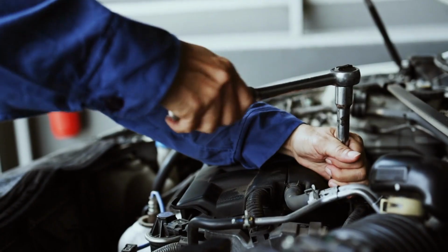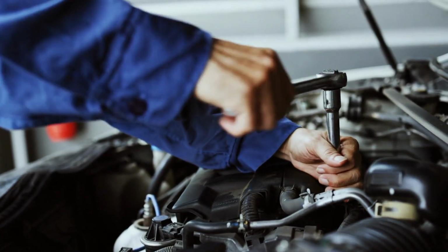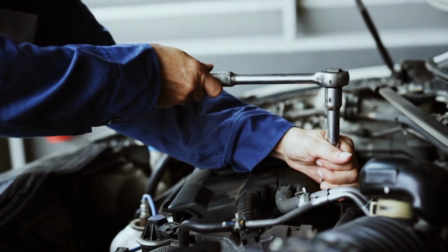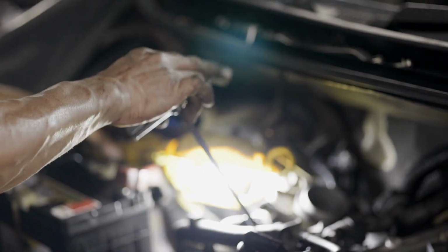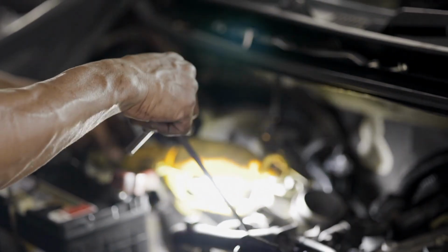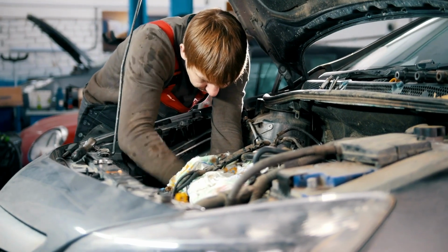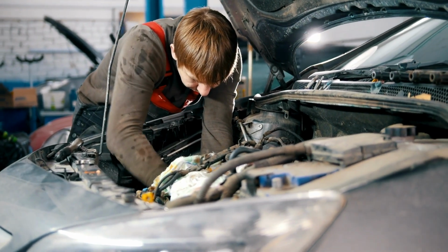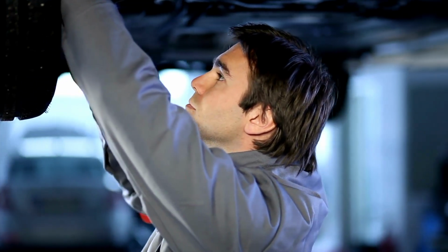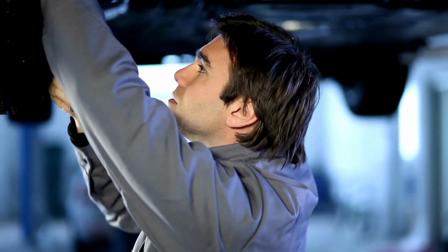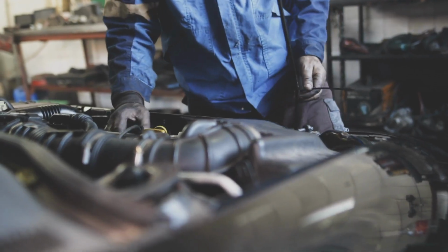What are the possible solutions for OBD2 code P0003? Replace the fuel pressure actuator if it is determined to be faulty. Check and repair any loose electrical connections or shorts in the actuator circuit. Inspect the fuel system for leaks and repair them if necessary. Test and, if necessary, replace the fuel pump. Check the fuel pressure sensor and replace it if damaged. Perform ECM diagnostics to ensure it is not causing the problem.